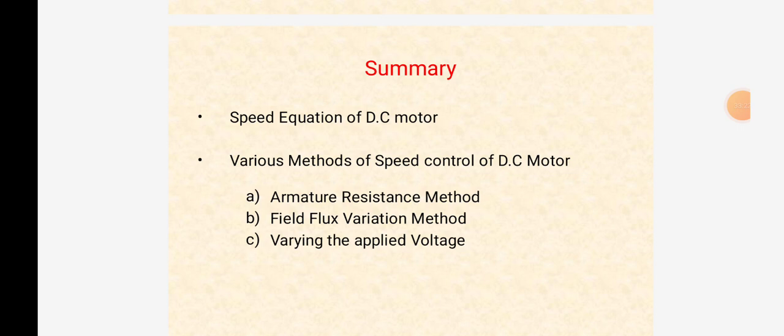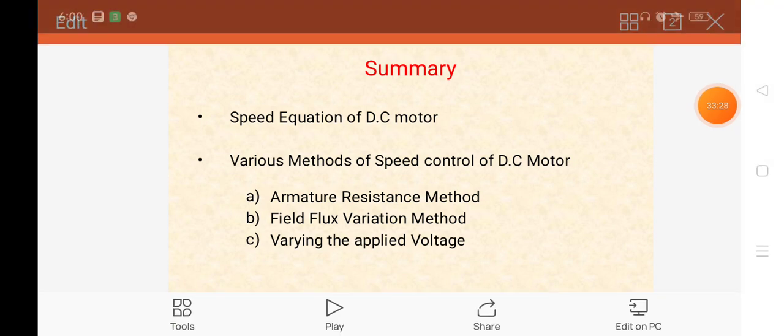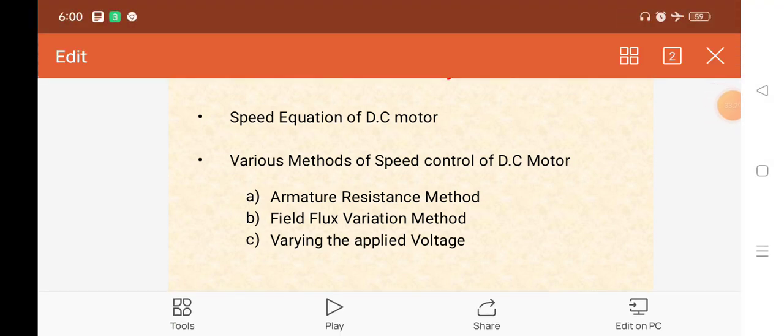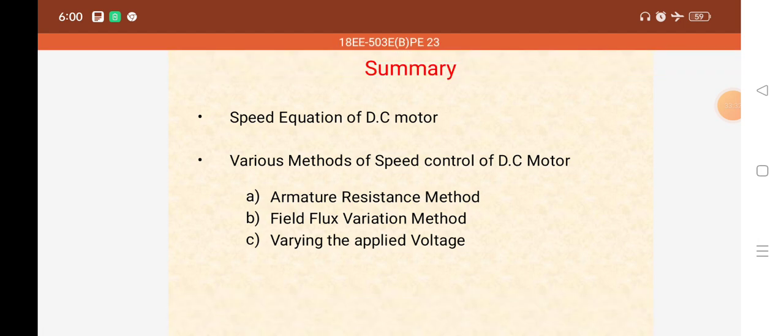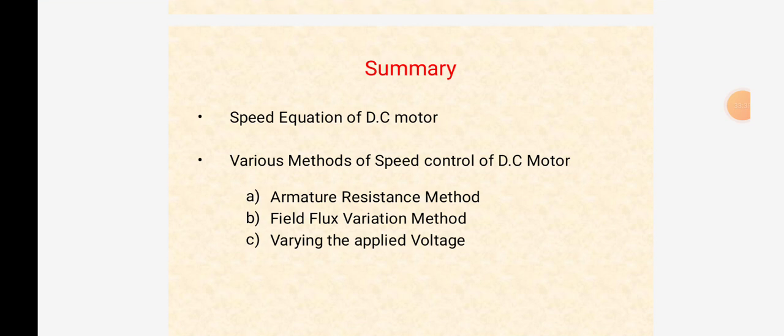And also these have the few disadvantages of electronic drives, that are the heat produced is more, it requires harmonic filters and active filters for reducing the harmonic content, hence it is costlier, it can cause noise pollution, the output power obtained from the drive is low, the initial cost of the system is high.